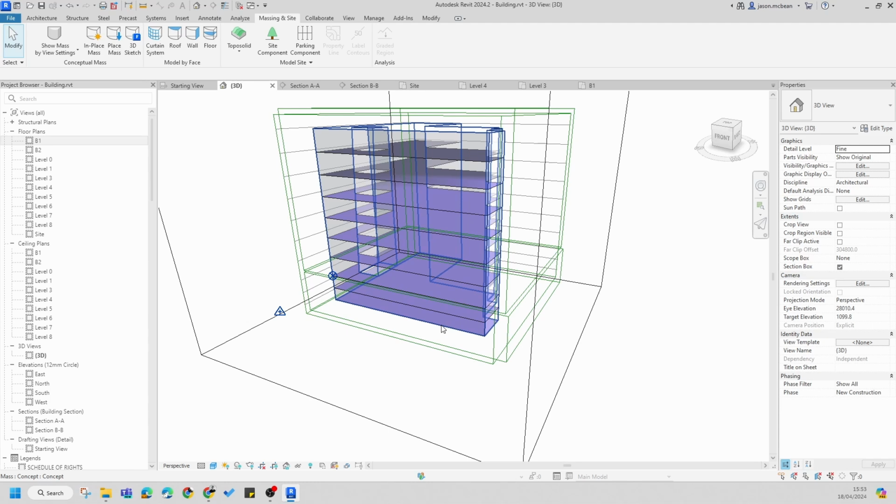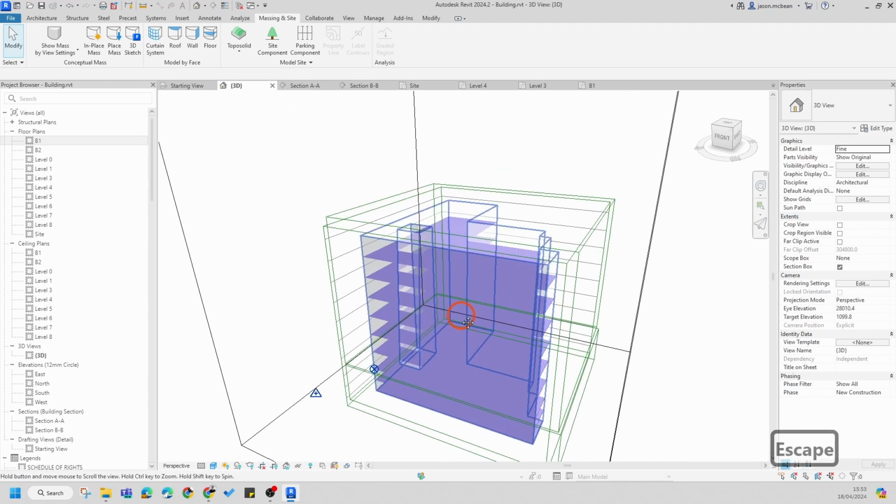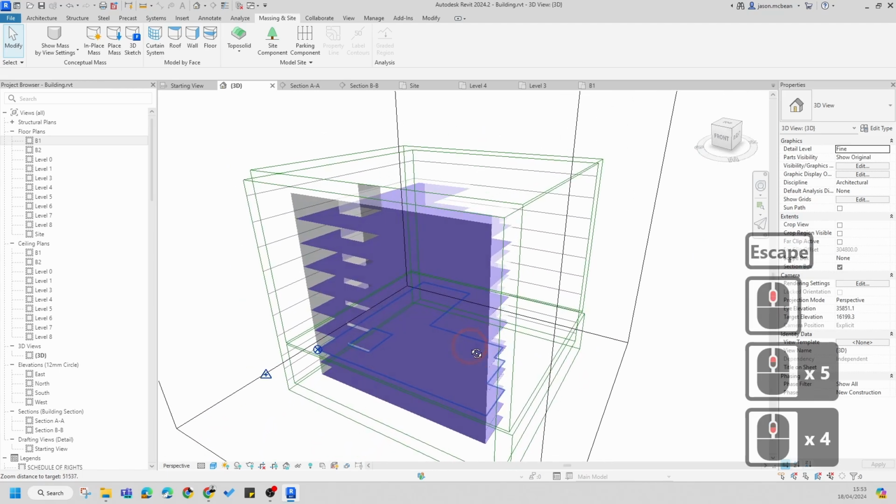You don't want to commit to a lot of 3D elements right at this point because you might have to do a lot of rework and undo a whole lot of information. So get your planning right, get the information right. I'm just showing you a quick method on how you can start drafting the information, putting information in the right place, dealing with information, so while you start modeling information, things will start to connect. Okay, so in essence, I'm just going to use 3D floors just for the time being to illustrate this.